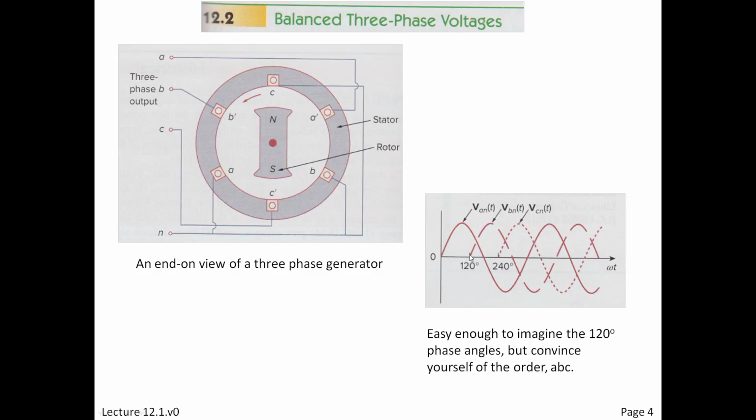So when you're trying to find phase angle in this arrangement, B is the next one encountered. Why? Because after A, the next positive or positively oriented piece on the stator that you hit is B. You're hitting the negative part of C. Then next you hit the positive part of B. Look, physically one third of the way around the stator.